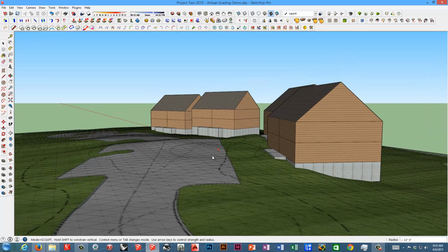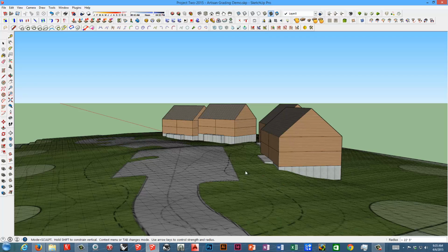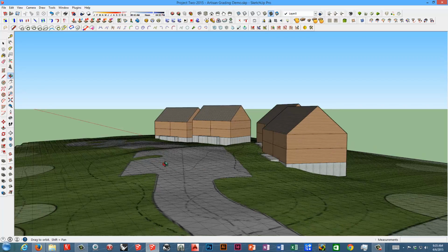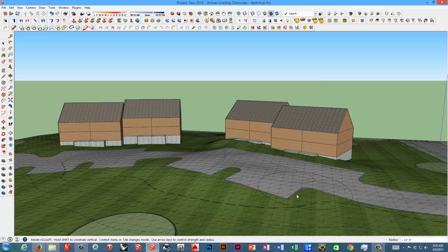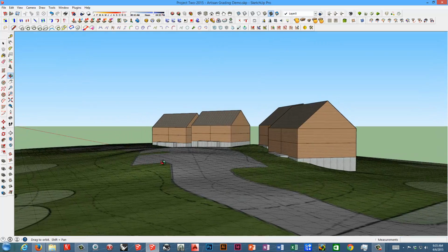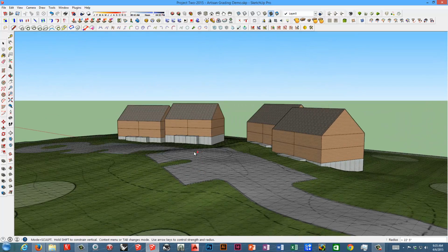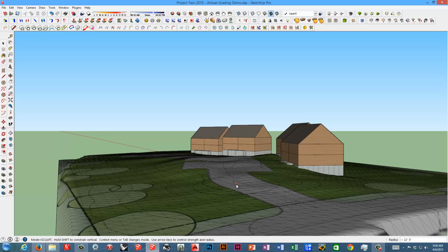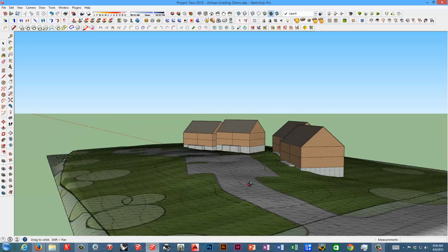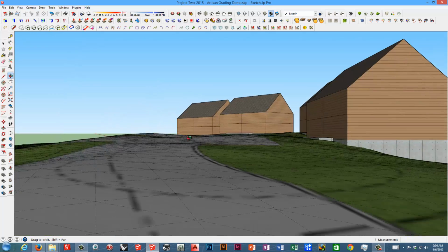And because I've got this image mapped on here, this is what's kind of interesting about it. If you try to do this by draping the geometry on the roads or on the terrain model, what you end up with is the geometry will start to distort as you start modeling or molding the landform, and then it doesn't really work very well because you can't really see what you're doing. So I found this method of actually putting on an image of it, which just bends and flows with the landform itself.